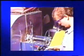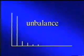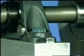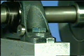During a balance job, the phase readings may be steady and then become erratic after a correction weight is applied. This is because a looseness condition existed at the beginning of the balance procedure, with the force of unbalance pulling on the rotor, holding it in a firm position and masking the looseness. Once the force due to unbalance is reduced substantially, the rotor exhibits looseness as the dominant condition, which then minimizes the effectiveness of further balancing. When performing phase analysis on a machine, remember that looseness can exhibit a directional phase of 180 degrees between components and erratic phase indicating rotating element looseness.